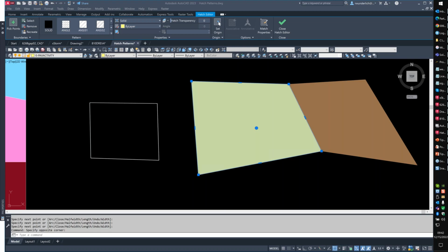How to export a line style and edit the line style in a drawing. Leo, that is going to be a much bigger prospect. I have a Lisp routine that allows me to extract line types out of a drawing, and then that creates a .lin file, and then we have to go back in and modify the .lin. That's a bigger issue that we would have to cover, and that might be a good webinar. My suggestion, Leo, submit that over to Lori, so you might get a $50 gift card out of that.